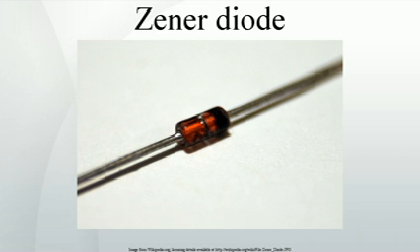Because of the low impedance of the diode when operated like this, resistor R is used to limit current through the circuit. In the case of this simple reference, the current flowing in the diode is determined using Ohm's law and the known voltage drop across the resistor R. The value of R must satisfy two conditions. R must be small enough that the current through D keeps D in reverse breakdown. The value of this current is given in the data sheet for D.